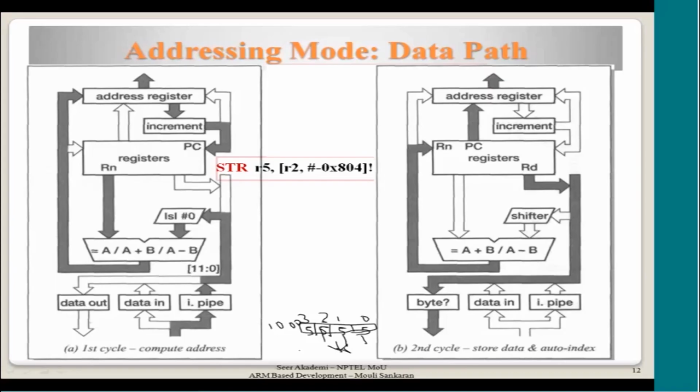So this signal is provided, and if it is a byte access, this will get activated, and then the LS byte will be taken and replicated in all the data buses, D0 to D31, right? So it will write the same byte value into all these positions and give it to the memory. The memory can decide based on the address which is coming out here. So the address, whatever, 1001 or 2, will come out through this, and data will go out through this. So these are the data bus and address bus. Okay, I hope this is clear to you.